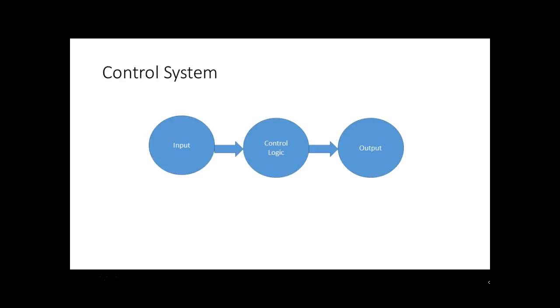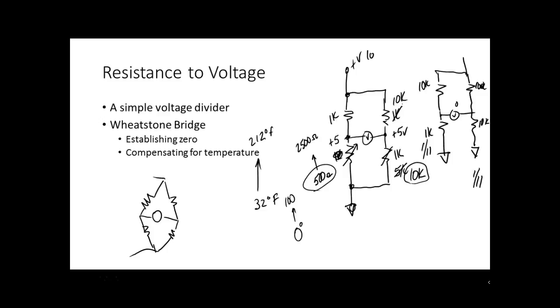So we okay here? Everybody okay? So Wheatstone bridges, we use that when we have to establish a reference, right? If we don't have to establish a reference, then a voltage divider would be fine. But both the voltage divider method and the Wheatstone bridge method are taking a sensor whose resistance varies according to what it's measuring and converting that into a voltage, which becomes usable now, right? Because we cannot transmit a resistance. So if we're going to send an analog quantity, we have to send it represented as a voltage or a current.